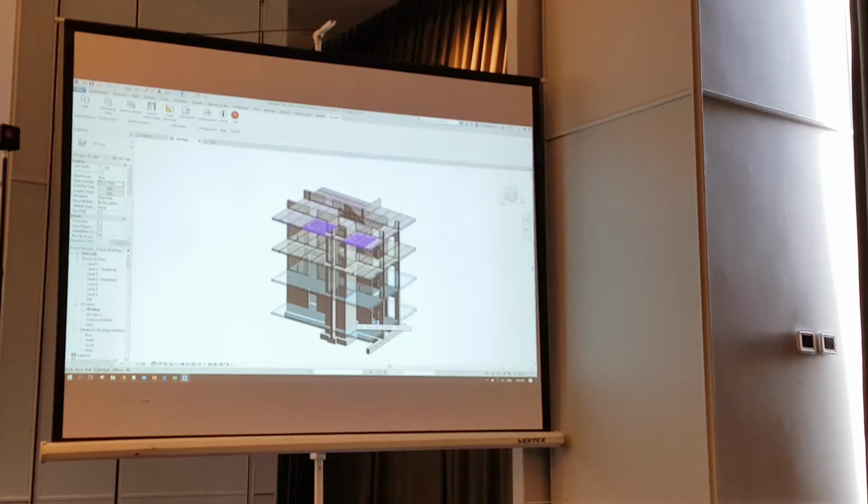What I want you guys to do here is very simple. Just click on the slabs on level 2. Alright? If you look at it, this is a Revit component slab. Now, there's one key point about the precast extension. They can only convert your structural model, not your architectural model. Okay? So this slab here is not an architectural floor, but a structural floor. The wall there is not an architectural wall, but a structural wall. Alright? So you guys need to change your architectural model to a structural one if you want to convert it.